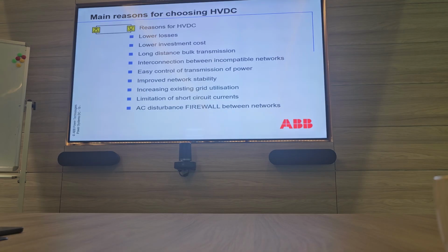Sometimes, like when two countries are separated by the sea, then we need to use underground cable. Like Saudi and Egypt, which are separated; there is a submarine cable there. Some countries where the distance is very short will go with UGC. In general, LCC, the current source converter, mostly uses overhead lines because it carries more power. VSC normally goes with cables, because VSC is also less power, only 1000 megawatt, and the voltage is sometimes only 400 or 500 kV.